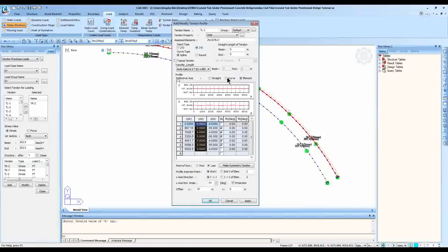One minor difference between the curve and element is when you actually draw the element, the element itself is straight. As mentioned in the beginning, in an FEA program, elements cannot be curved. That's not a proper type of component in a 3D FEA program. So every single element is straight.